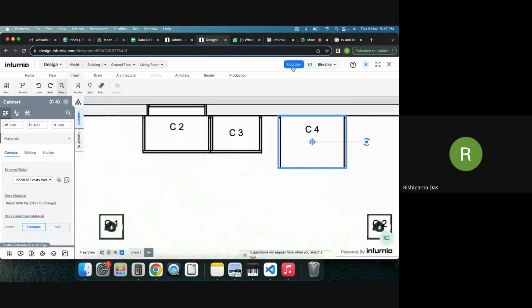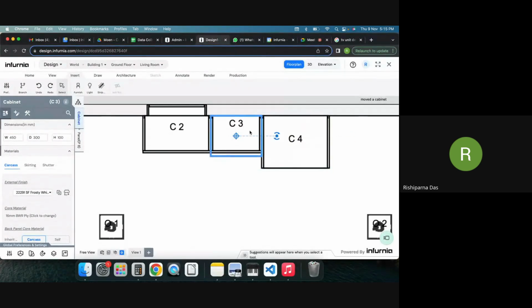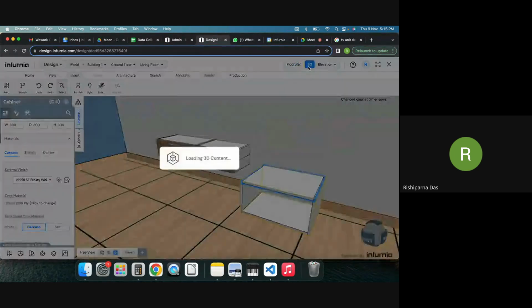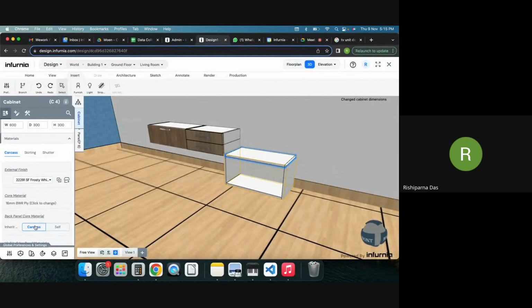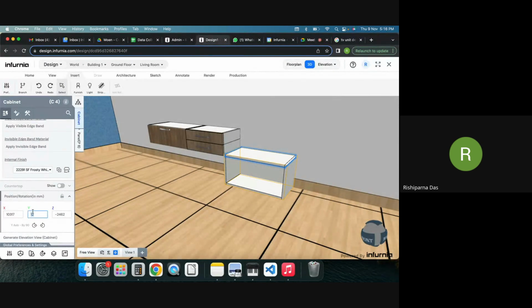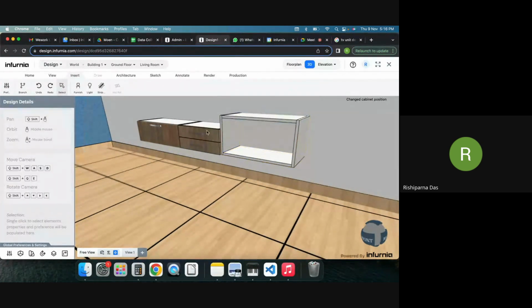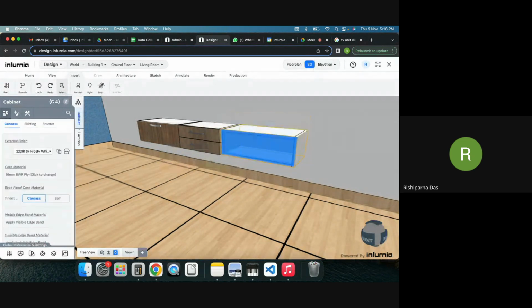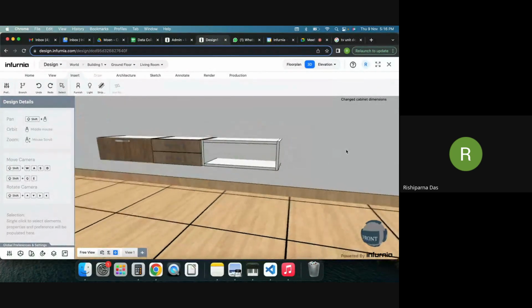So we'll go into floor plan, and here we'll place it next to the same thing. We can see the depth is 300 here, so we will match it to 300 mm. And when you see in the 3D view, the position and rotation in Y, you can make it 300 like how we had done, right? And the height of it here, it's 100 mm, 100 mm to 200. So this one also you can make it 200. So you can see that it is coming accordingly.